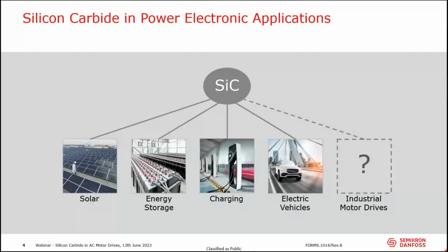So why is that? Of course, cost has always been an issue. Then also lifetime considerations. Electrical drives or standard drives typically require some short circuit ruggedness, which was not necessarily given in former chip generations. Also, many people still think that silicon carbide only makes sense if you switch it really fast, meaning high carrier frequency and also very fast voltage rise times. Some of these things are like they are, but there are things also changing.